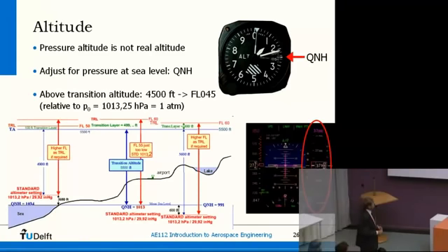And there are a whole different sets of wordings for that. You have the QNH, which is the sea level pressure, gives you the actual altitude with regard to sea level. And this is what we normally use. Of course, in our country, it doesn't really matter whether you use sea level or the airport, because they are about the same. But otherwise, you have to use the other setting, the real setting relative to the airport.